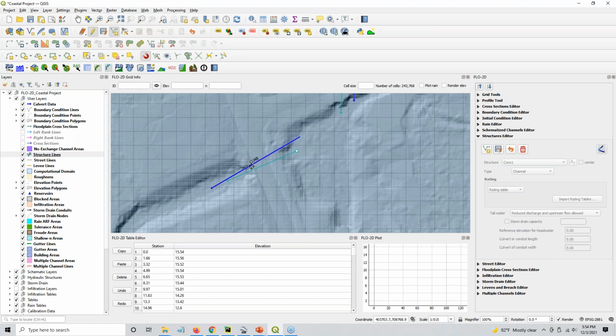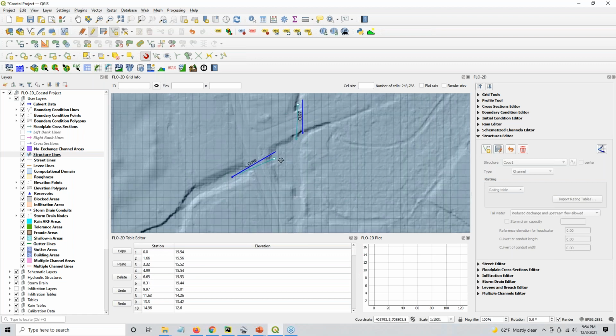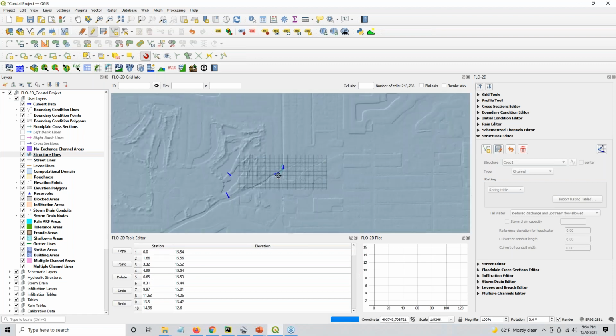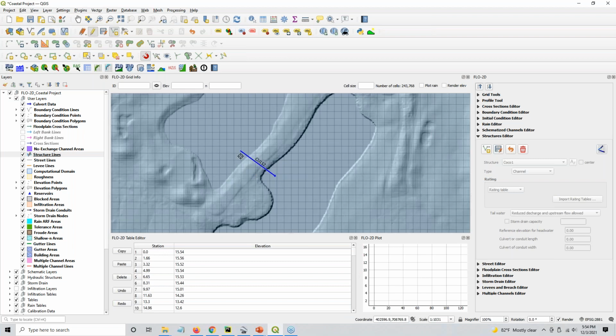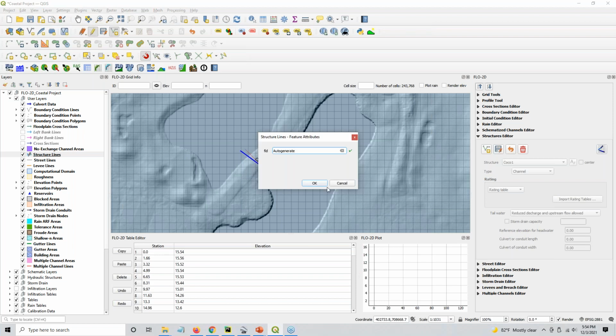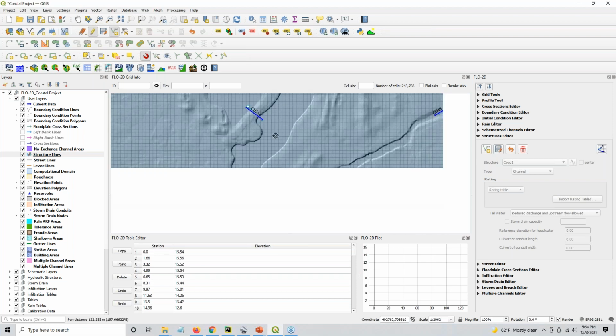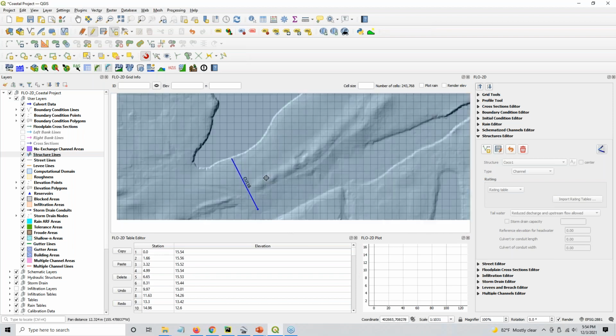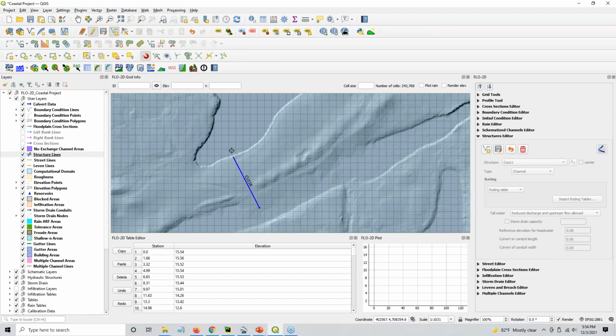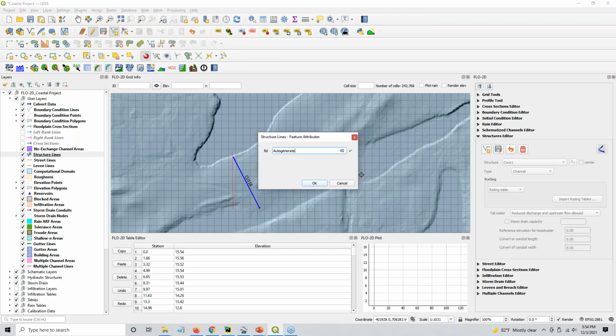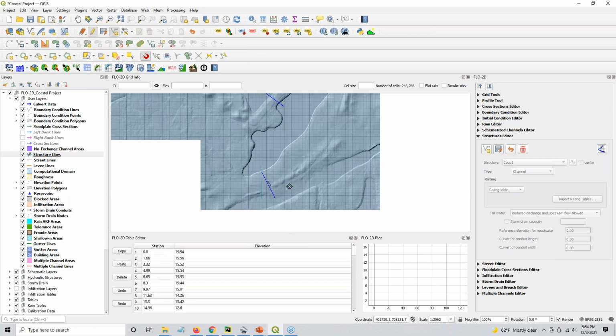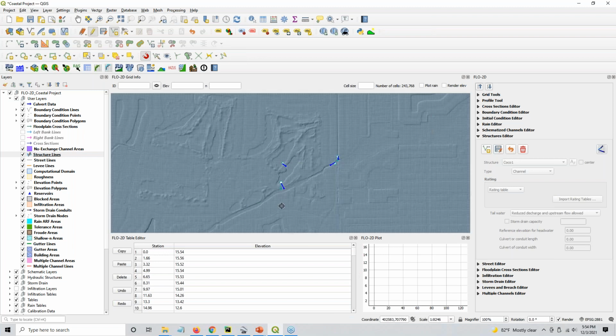These ones tell you kind of the general location of that culvert, but I'm going to show you kind of the desired location. This one here, from here to here is probably good. And this one here, see, it's not any good because it's on the wrong cell. So I'll go here, and then if you look, it looks like it comes out right about here, not right here. And then I'll right click on that, and that takes care of those 4.